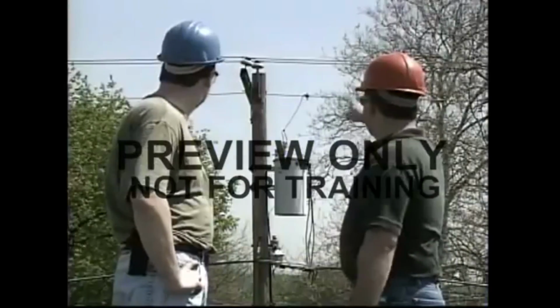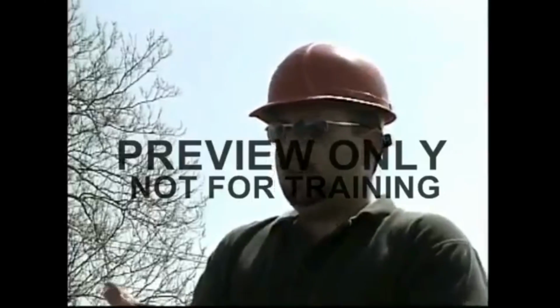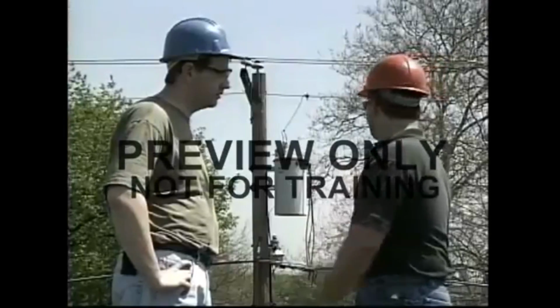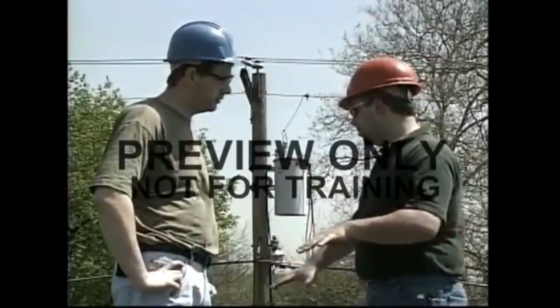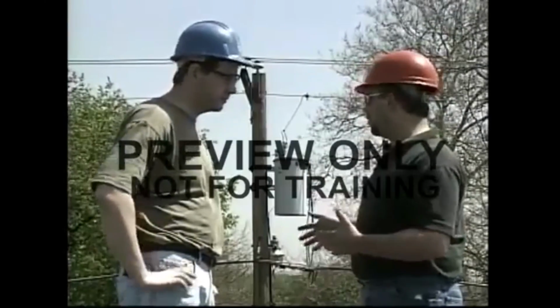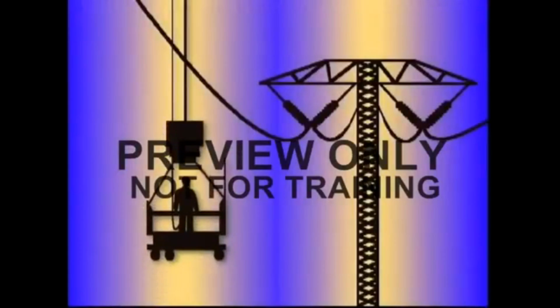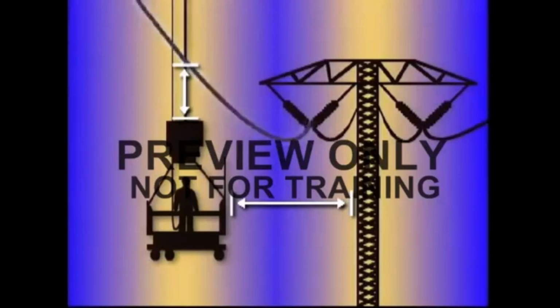Electrocution can also be a hazard when you are working on a suspended scaffold. Make sure you are a safe distance from all electrical sources. Be especially aware of any nearby power lines that could come in contact with the scaffold. The rule for working near power lines is the higher the voltage, the further away you should be. Ask your supervisor about how far away you should be from any lines around your worksite.